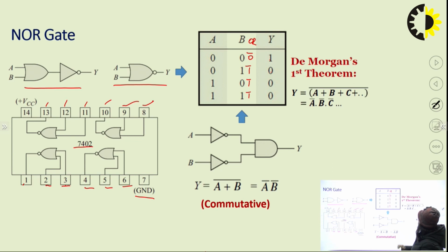And if we talk about the property, De Morgan theorem can be applied for this IC, that is, (A plus B) bar can be opened using De Morgan theorem to write it as A bar dot B bar, and using this logic we can draw the circuit using basic gates: A bar dot B bar is an AND gate with inverted inputs, that is NOR gate.